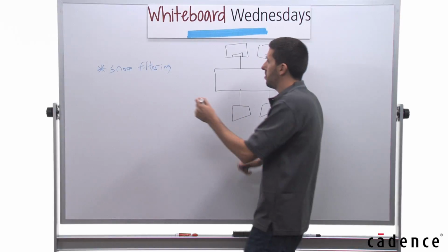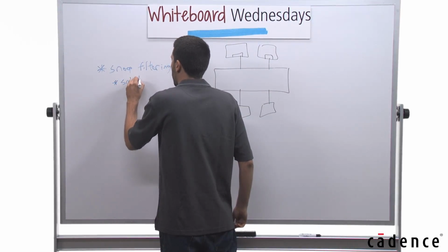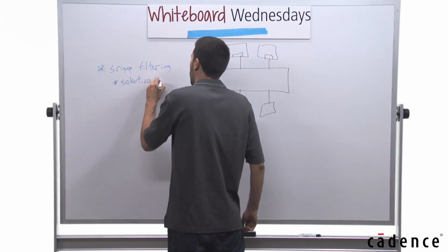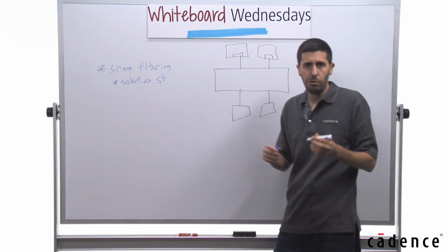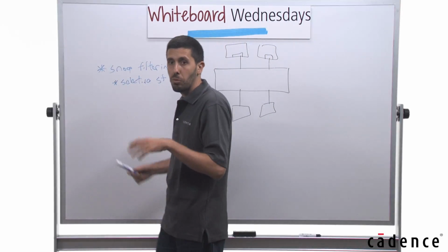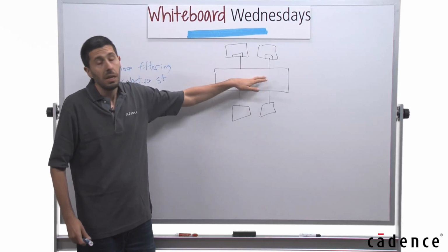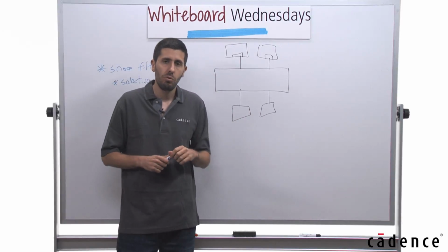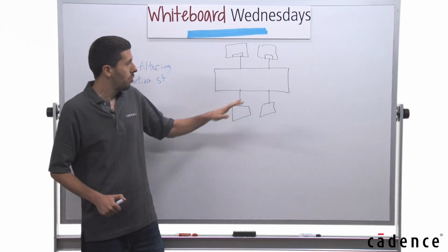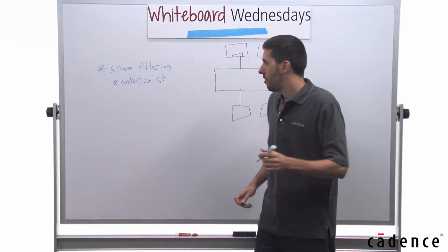Some designs implement a selective snoop filter. And by selective snoop filter, I mean a snoop filter that is not active for all transactions. A certain type of transactions go through the normal process of being snooped to all available masters. And some transactions go to specific masters according to the snoop filter. So we need a way to configure that.